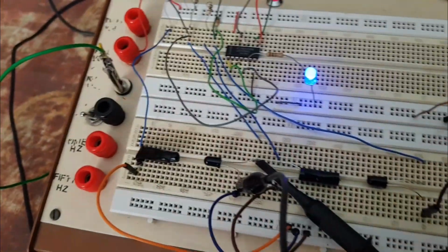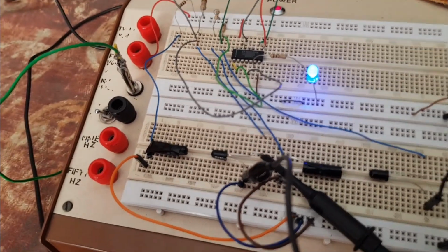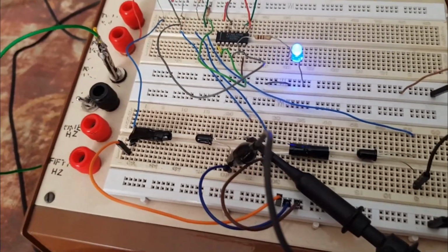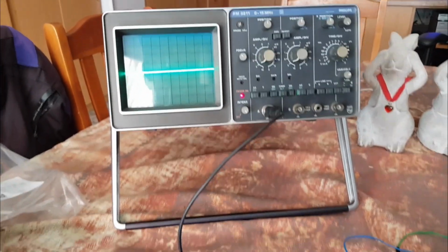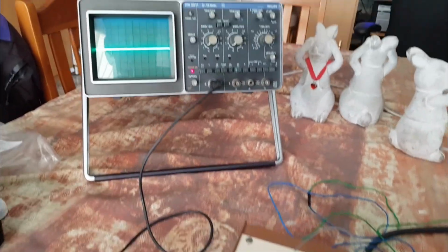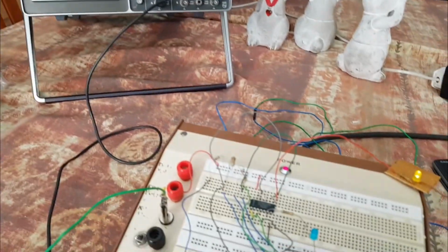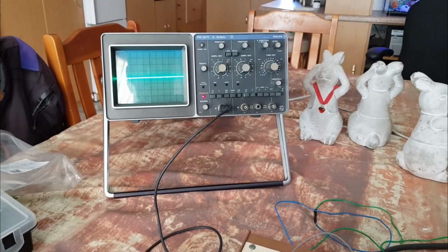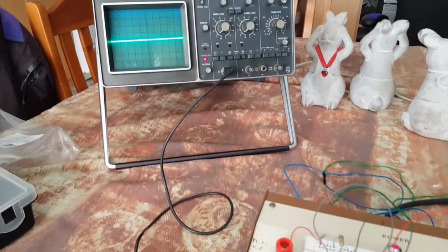Because of the way this is wired and the photosensor is put in reverse, when the light is coming through, we should see a low on the oscilloscope, which is what we do see when looking at it. Whenever we block the incoming light, we should see a high. And there you can see clearly that when the light is being blocked, we are receiving a high. The same will be on the other photosensor.